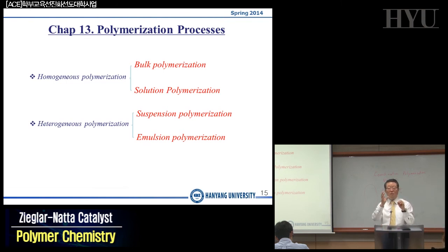So you have to recover as much as possible. The solvent is an issue, and the residual solvents should be a disadvantage of the solution polymerization systems.